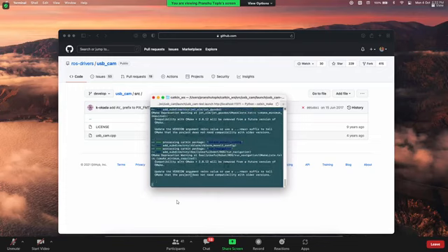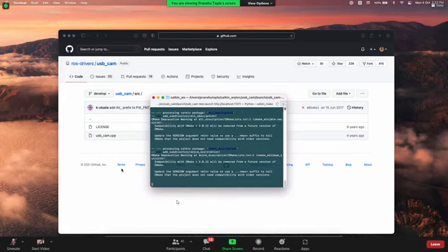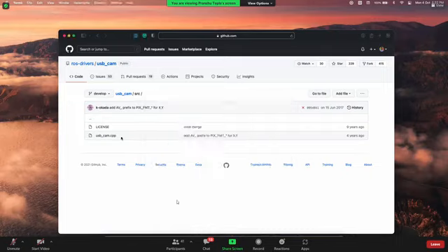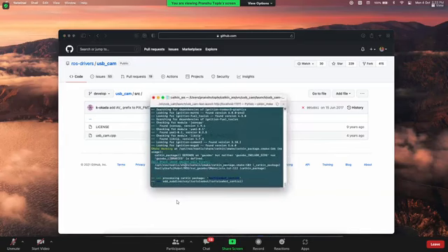So many people ask me, I sometimes do catkin make, sometimes I don't. Whenever there is a C++ node, you have to do catkin make. If it is a Python node, it's okay if you ignore that, because Python takes the recent version of the script, but C++ nodes take the build version of the script. So that is the reason you have to do catkin make or catkin build.